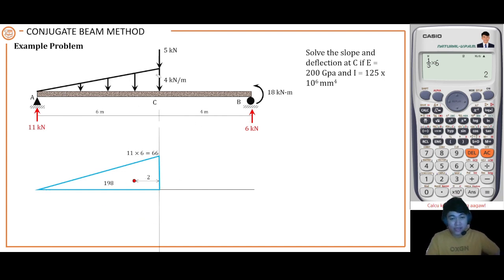Next, we have here a trapezoidal triangular load. The moment diagram by parts of the triangular load is a second degree spandrel, from 0 to a certain magnitude at your reference point. Now let's identify the intensity of this spandrel load. All you have to do is take the moment of this triangle about your reference point.